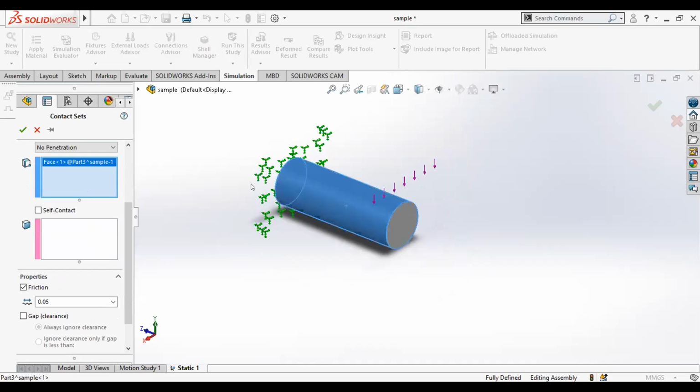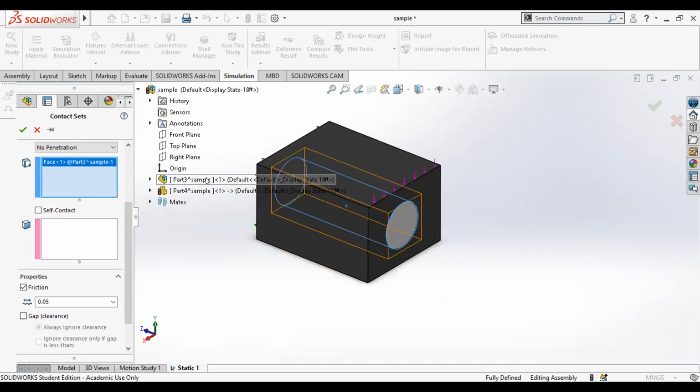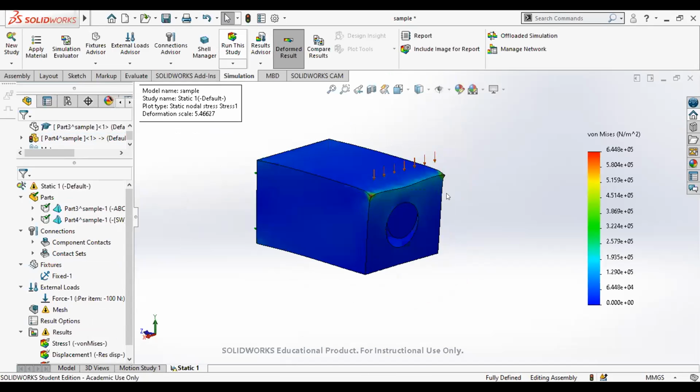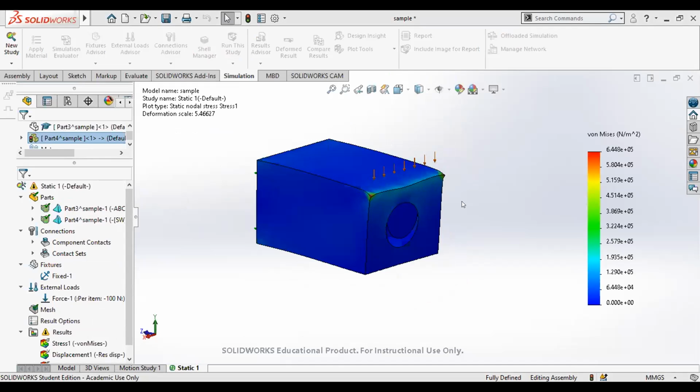Let's say I put here, what are my components? Maybe I put the contact here. Under connection, you need to define the friction between these two materials, because now you have two materials involved. It will be slightly different if you run assembly models, where the assembly has different materials and different components in one single body. So you need to decide on the connection, or what we call the contact, between the two components.